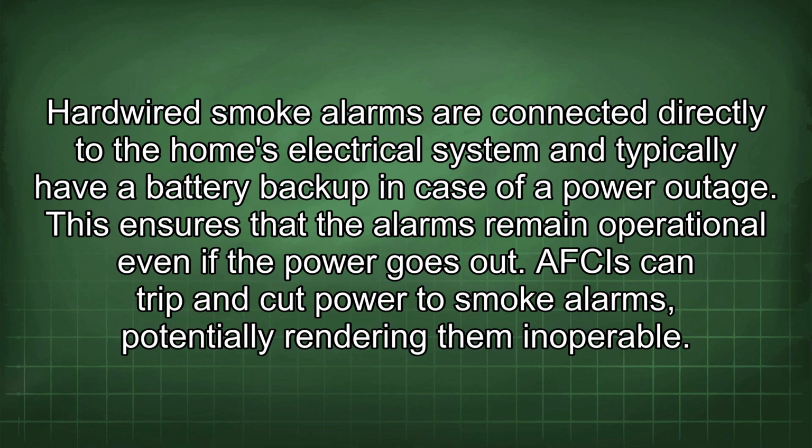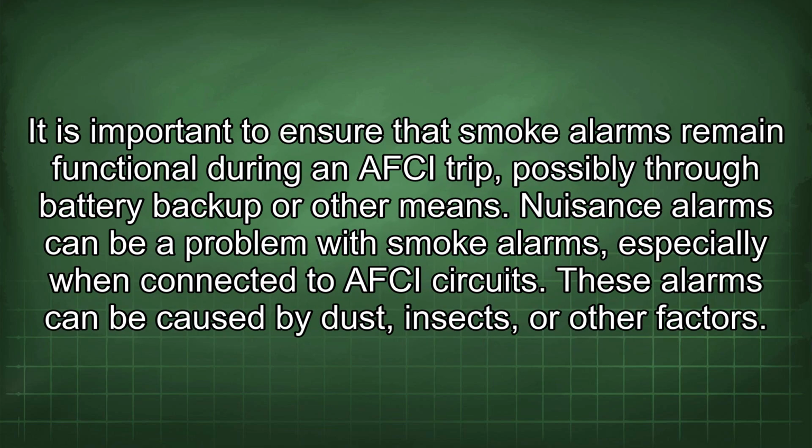This ensures that the alarms remain operational even if the power goes out. AFCIs can trip and cut power to smoke alarms, potentially rendering them inoperable. It is important to ensure that smoke alarms remain functional during an AFCI trip, possibly through battery backup or other means. Nuisance alarms can be a problem with smoke alarms, especially when connected to AFCI circuits.